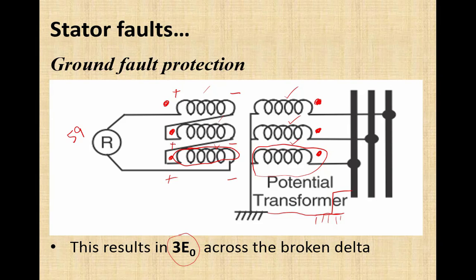That was around 21, 22 or 23 volts. So that was actually third harmonic voltage. The question is why that voltage was appearing here across these broken delta points when we have removed all the capacitances. In the presence of capacitance, there will be no such voltage.